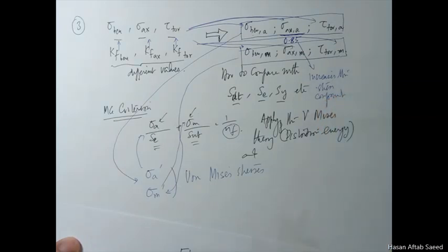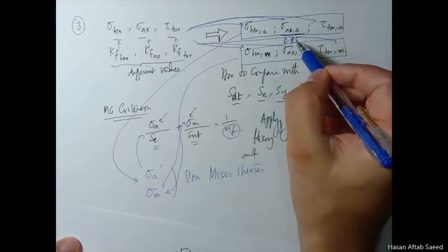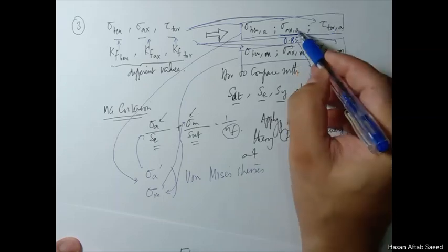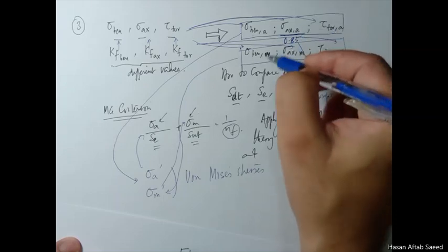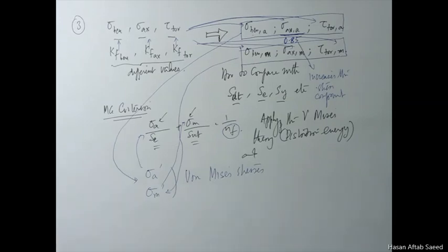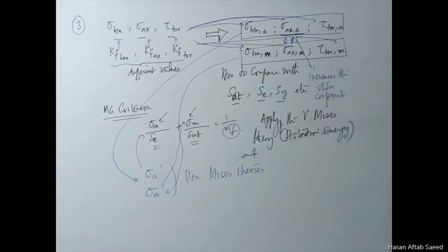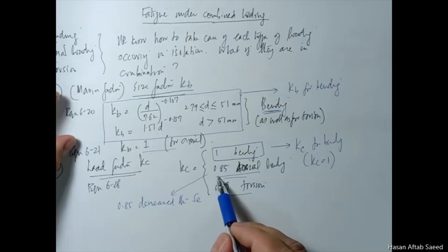You essentially do the same thing: instead of decreasing strength, you increase stress, and because stress can be increased on an individual level for axial loading only. For axial loading also, only the amplitude component, and these things are tried and tested empirically, so there's a sound practical basis behind it. So you increase the stress component, and so the effect of this 0.85 is applied.